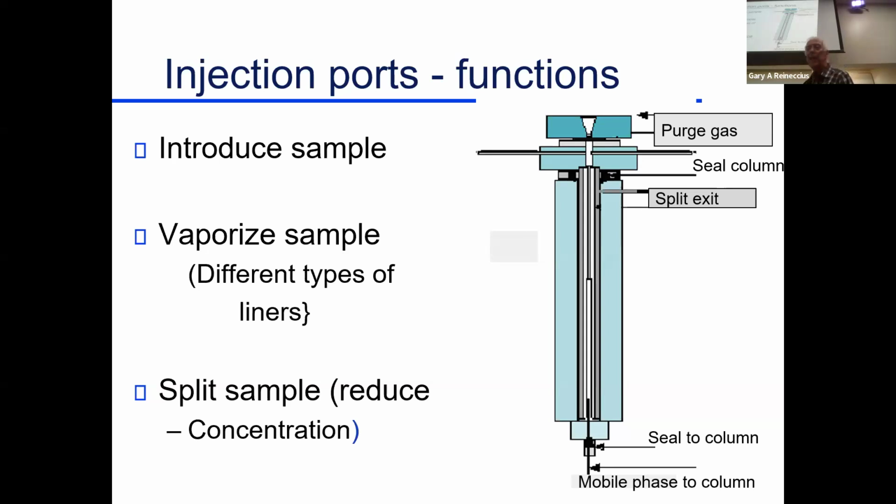Up at the top where you take your syringe and go down and pierce that also. Do that a few times, and again, you have another opportunity for this gas to leak out. So again, this kind of maintenance, we need to replace particularly those 2 seals up there.